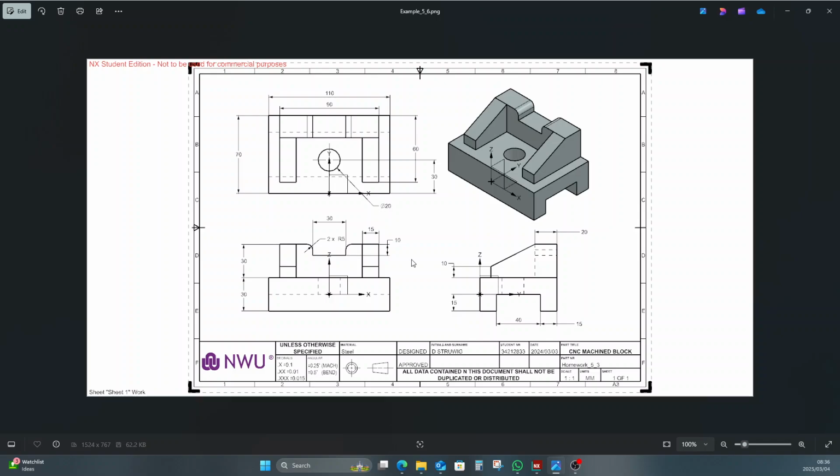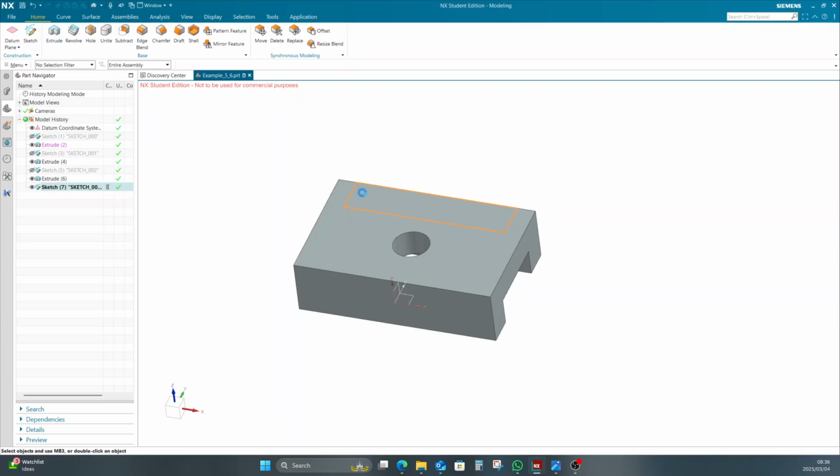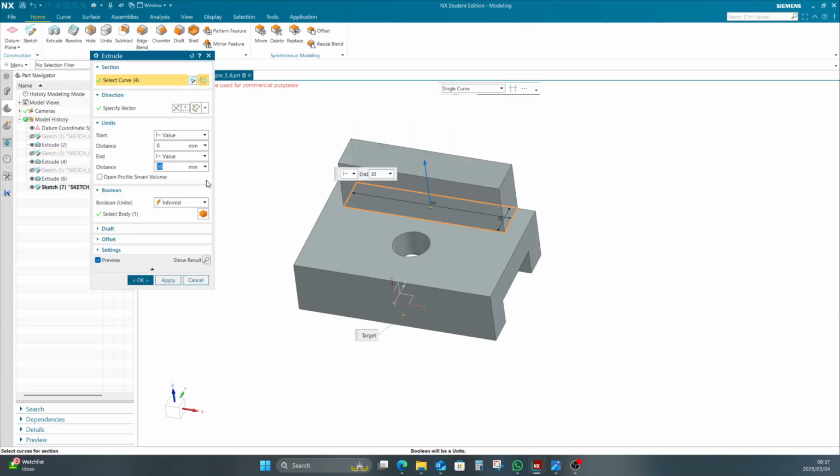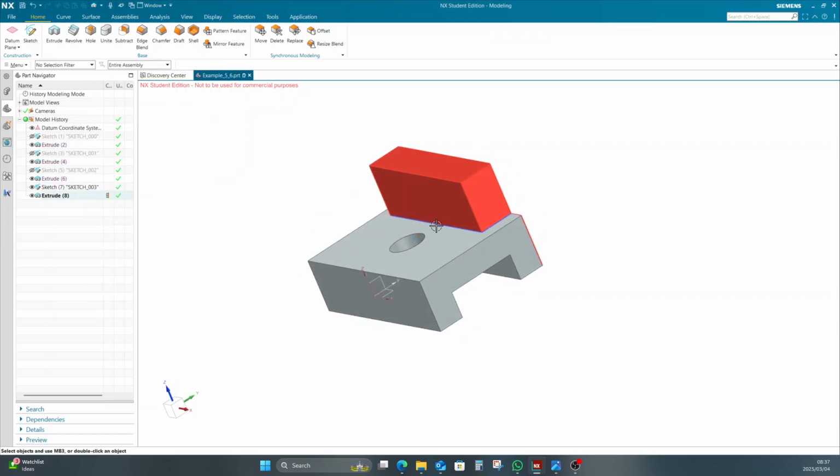You can see, let's see how high is it. So it's 30 millimeters upwards. So I'm just going to extrude that curve 30 millimeters. I'm going to use my unite tool, which means that it unites this part, which I'm creating now, onto this body. So by uniting that, now this entire thing is united, so it's one object, and that's important when you